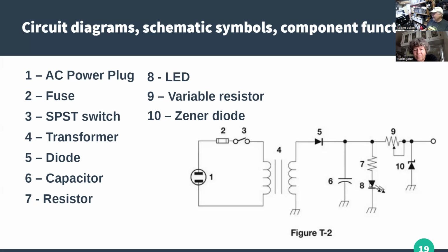It's going to light up this LED showing that there's voltage. And this potentiometer is going to control the amount of current, because this Zener diode is going to have a fixed voltage at this point. Not that you needed to know all of that.